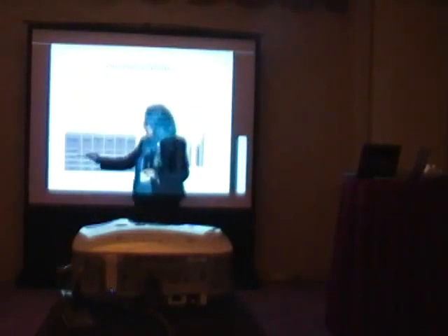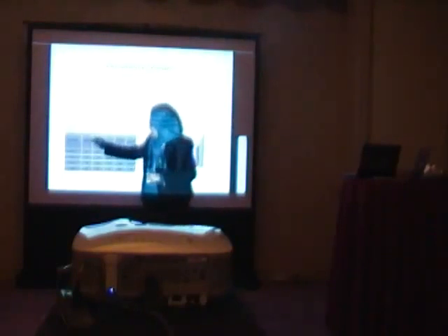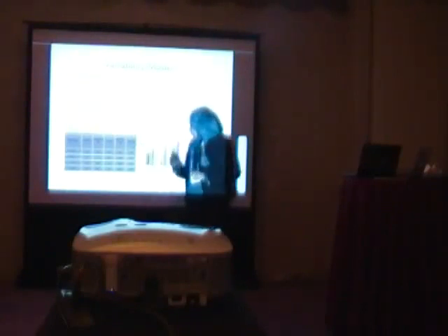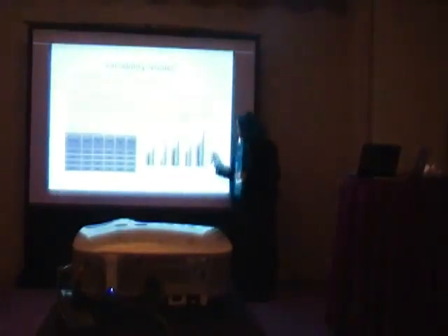This slide shows some results. We compare our work to the work in 6. Here, at different technologies, 65, 55, 45, 32, 22 nanometer technology. This is the random component of the delay. It's 35%, 37%, 43%, 34%. This is the systematic component of the delay, and this is the total component. As we can see from the graph, as technology scales down from 65 nanometer to 22 nanometer, the systematic, random, and total deviation in the delay increase.